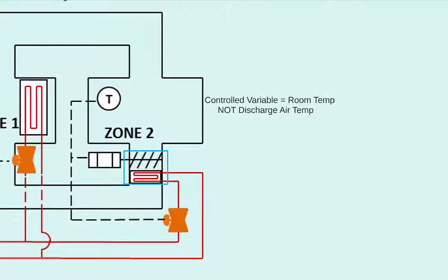In a reheat coil, the control variable is the space temperature, which is being sensed by the temperature sensor on the wall. I believe you'll be able to identify the rest of the components of the closed control loop, so I won't go there. But if you are unsure, pause the lesson and see if you can name them.